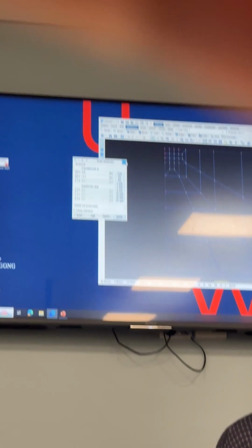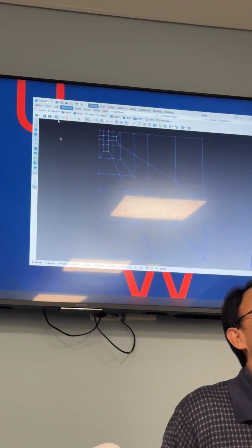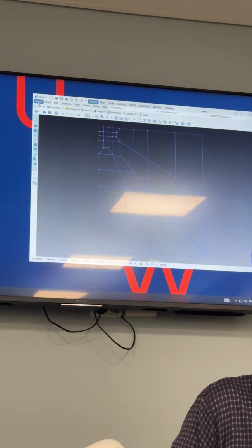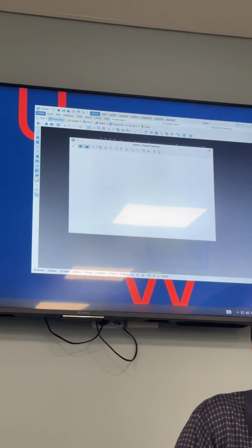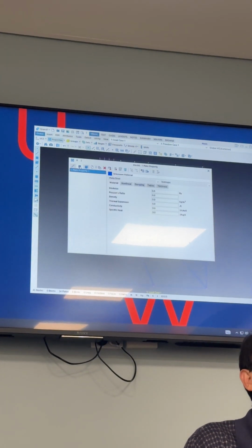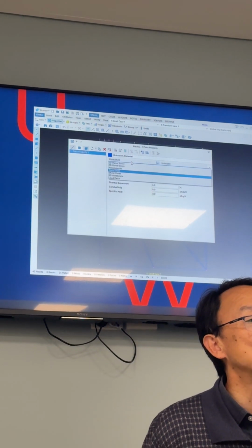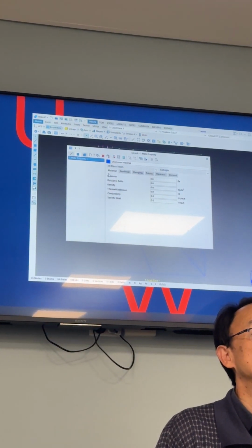After importing the boundary condition, you're going to import the material property. Import the material property from visual, global, you choose property. When you use this one, you need to choose this plate. When you choose the plate, you choose plane strain, isotropic.